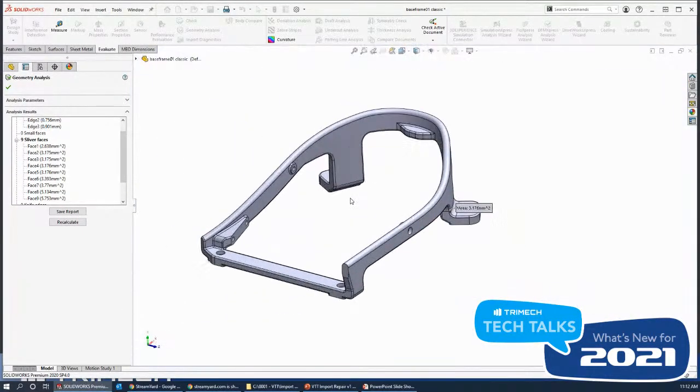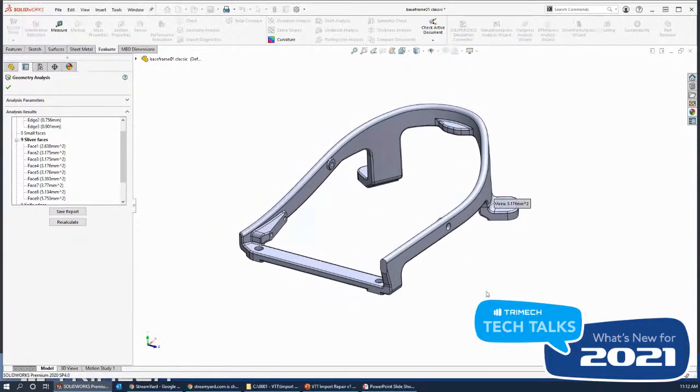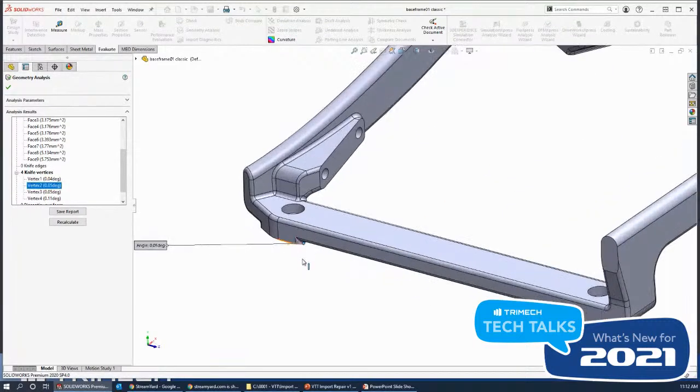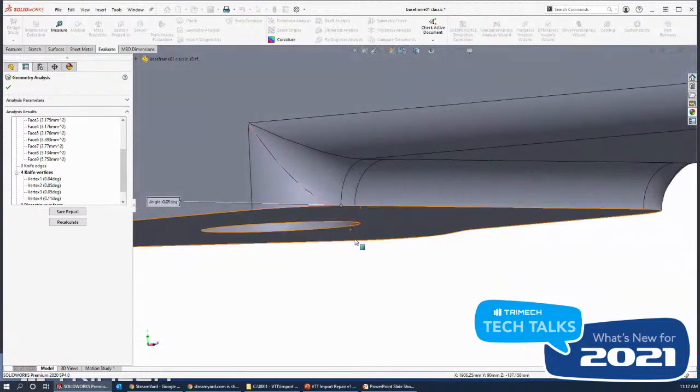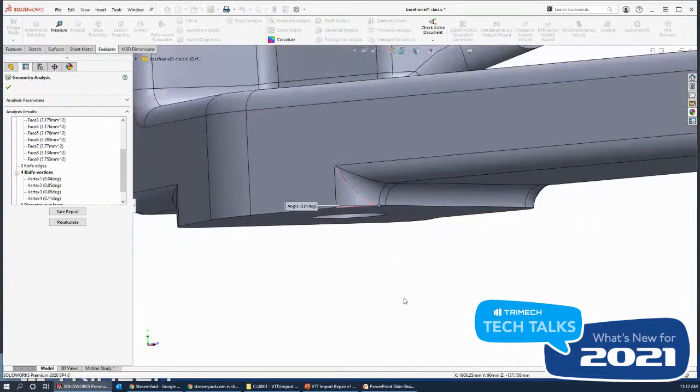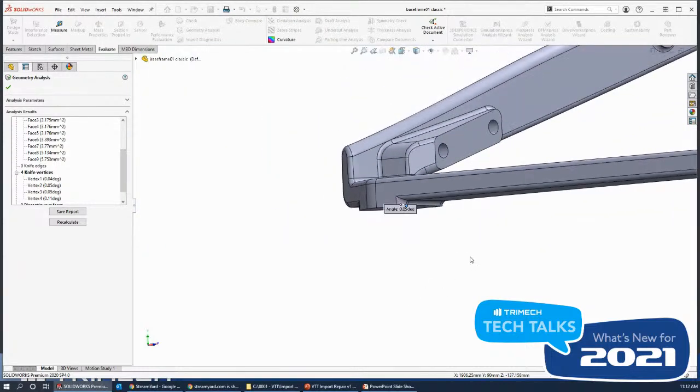Again, is this good geometry? Is it bad geometry? Am I indifferent to it? I guess it depends what I intend to do with this particular model. These knife vertices, which are very sharp regions where, for example, the angle peters out to 0.04 degrees, I know for sure that this neighborhood is going to cause me some heartburn if I were to try to create an FEA mesh.